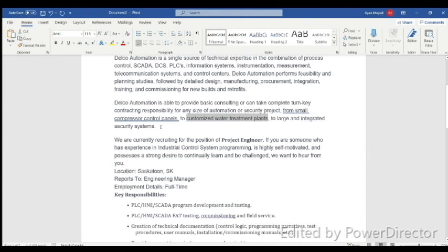We would also integrate security into the SCADA system using user groups, which we learned in the SCADA course. So we would create user groups for everyone who can access the screen, create their username and password, and then within these user groups we would create security codes for the screens and or buttons.